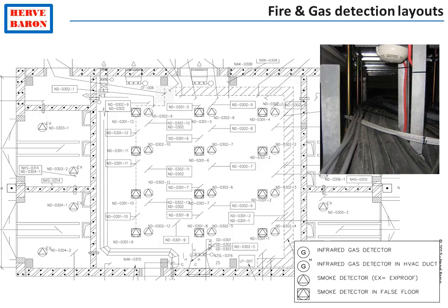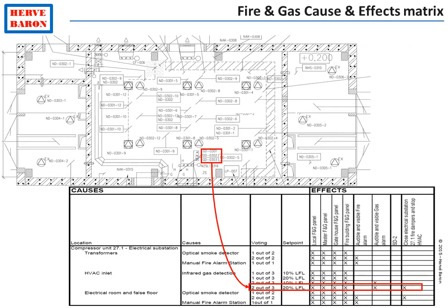Detectors are provided throughout the process areas and within buildings. The actions initiated upon detection are defined by safety on the cause and effect diagrams. Gas detection in the inlet ventilation duct of this building, for instance, is shown to stop the ventilation.